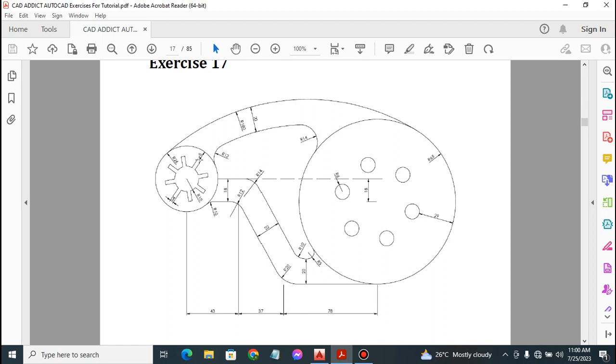So the distance of these protrudings from the circumference of this larger circle is 8 millimeters. So we'll take away 8 millimeters from the radius of the larger circle, which is 26. Take away 8 from 26, we'll be left with 18 millimeters. So the dimension of that circle is going to be 18 millimeters radius. So right now we're going to be producing two circles, one with our main line, which is of dimension 10 millimeters, another with a construction line of dimension 18 millimeters.